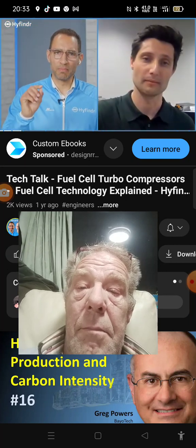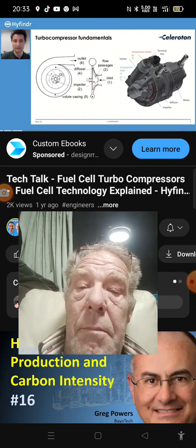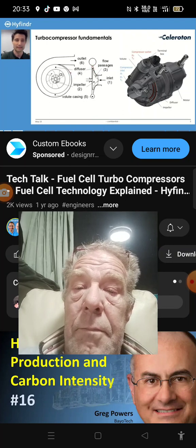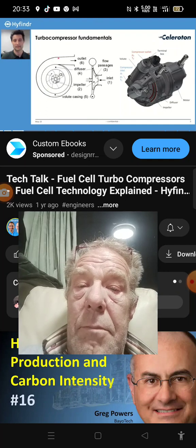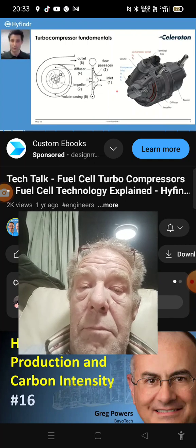So the impeller is number 2 on that picture. Number 2, yes, you can see it right here. The diffuser is number 4, and the spiral casing is essentially number 6. Understood. Okay, so maybe now we can briefly go through step by step what happens from a fluid perspective. At the inlet, which is indicated by number 1, the flow is directed towards the eye of the impeller, the center of the impeller.